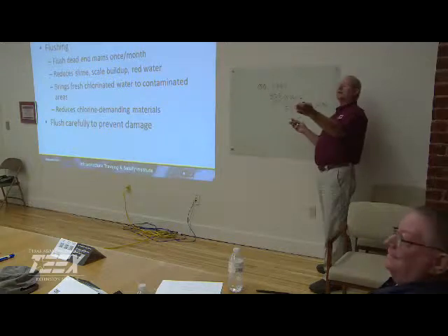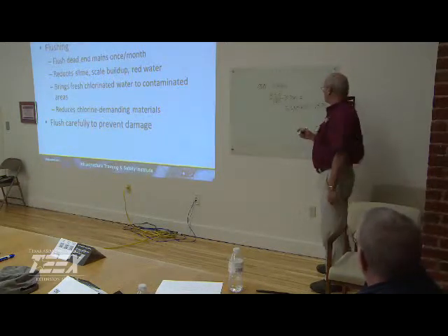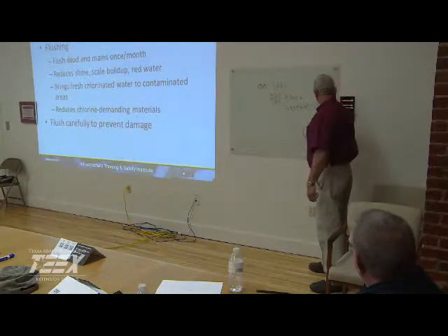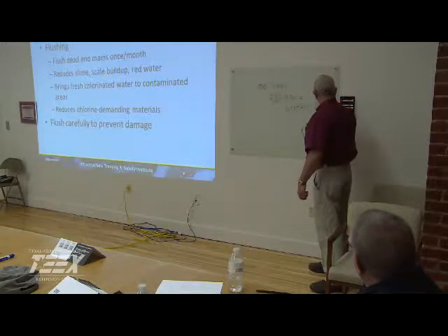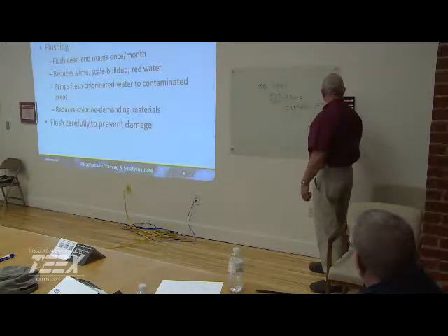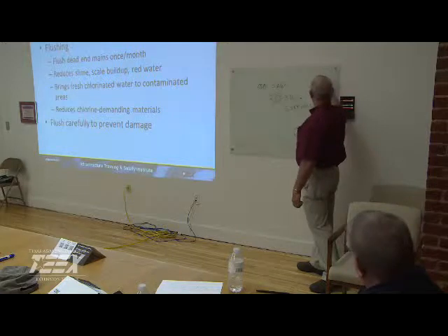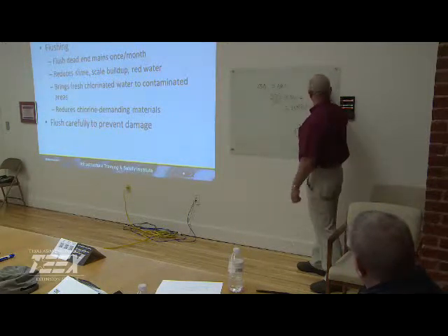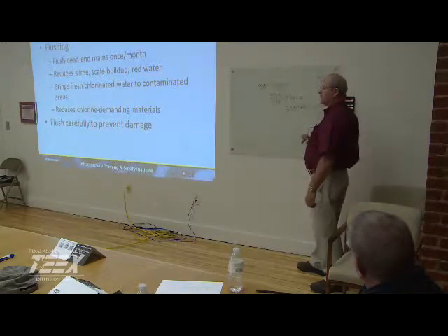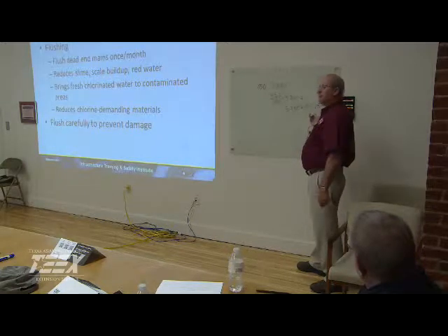Okay, now they recommend a minimum of 2 times the volume, times 2. That's 2,740 gallons. Okay, now 3 feet per second is minimum. They recommend 4 feet per second. Okay, so now I need to figure out time.